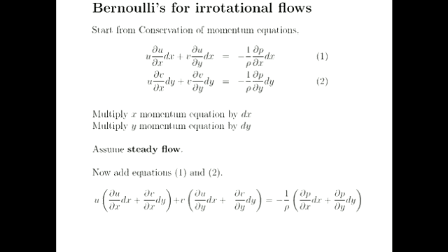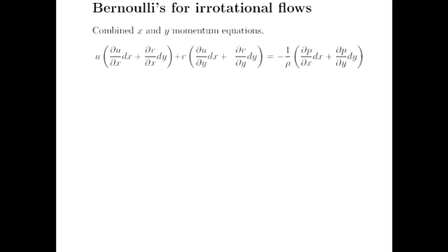That term, for a steady flow, really just reduces down to the total change in pressure, dp, okay? So we get this pleasing combination of terms, at least on the right-hand side of that equation. Now the trick here is irrotational flow, right? We know that for this course, all of our building block flows are purely irrotational, and we've proven that when we add those building block flows together, the resulting superposition is also irrotational. And you'll see that something really cool happens.